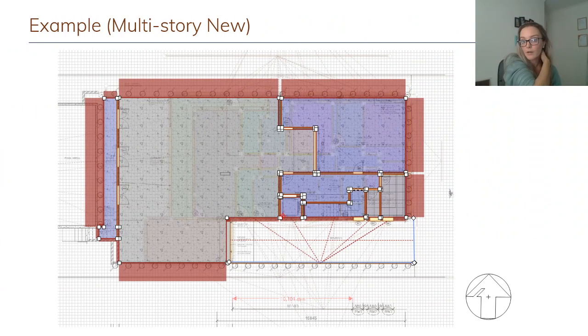So this is what a multi-storey dwelling looks like when it's modelled in First Rate 5. We take your floor plan and it gets transferred in 2D into the software. So we need things like wall construction, floor type, orientation, all these sorts of things to model the building. The grey area is a garage. The blue areas are other daytime areas. I think this might have been a gym or something. Storage areas, outdoor laundries or something like that.